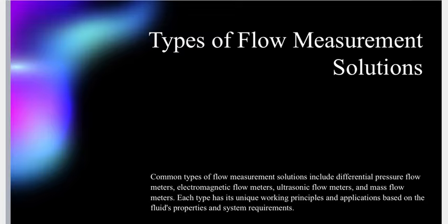The disadvantages: accuracy is affected by bubbles or particles, and it is more expensive than the basic flow meter. The applications are water distribution systems, also HVAC systems, and large industrial pipelines. It's for pipes that are large. The HVAC, I don't remember exactly what it is, but if I talk about it now, it would take a long time.